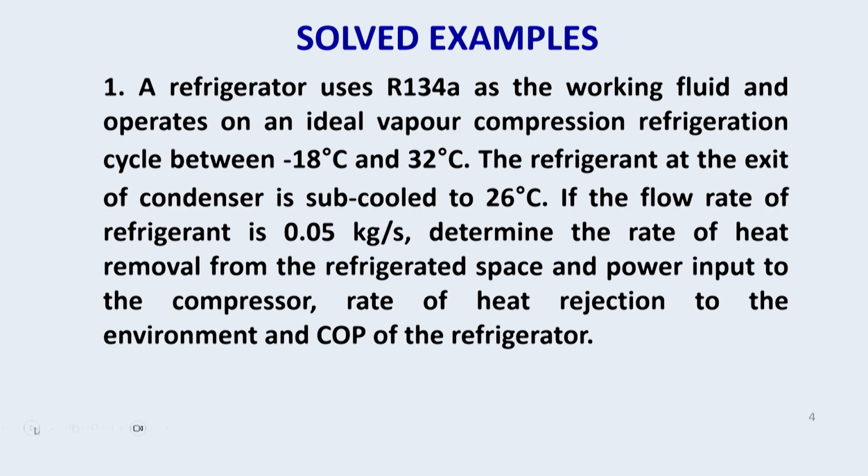The refrigerant at the exit of the condenser is subcooled to 26 degrees centigrade. Mass flow remains the same, 0.05 kg per second. Determine the rate of heat removal from the refrigerated space, the power input to the compressor, the rate of heat rejection to the environment, and the COP of the refrigerator.